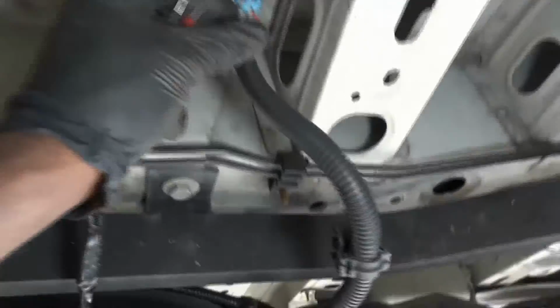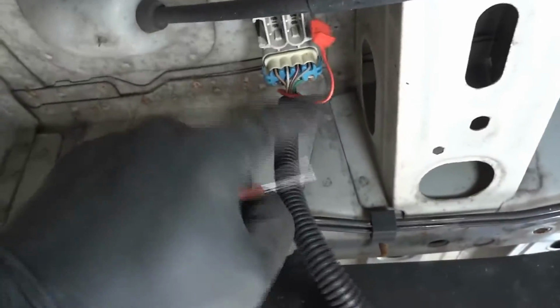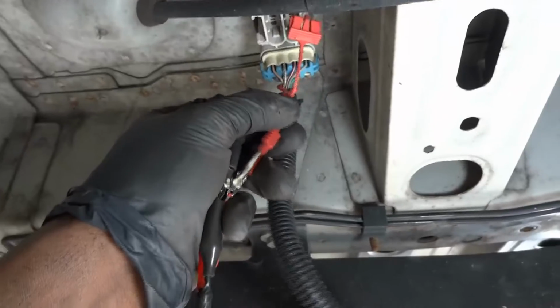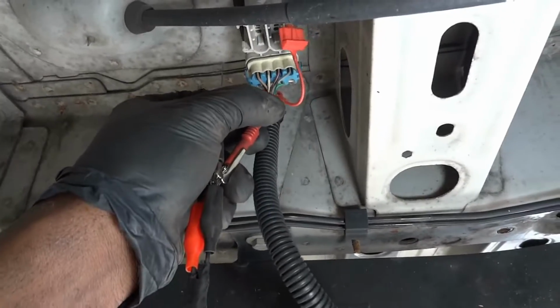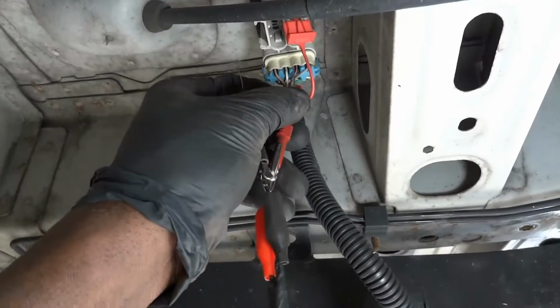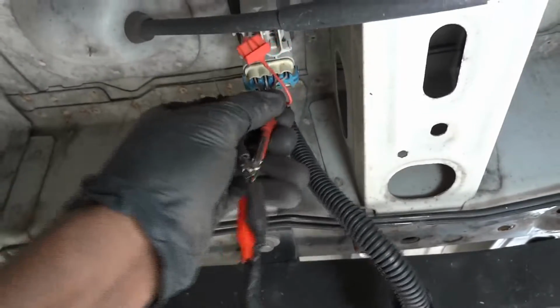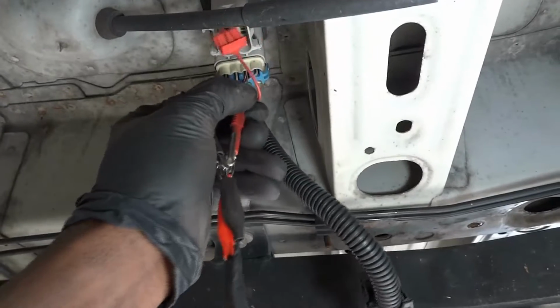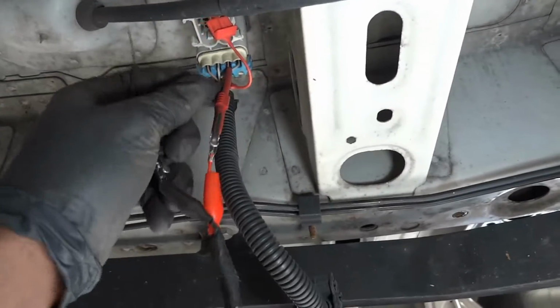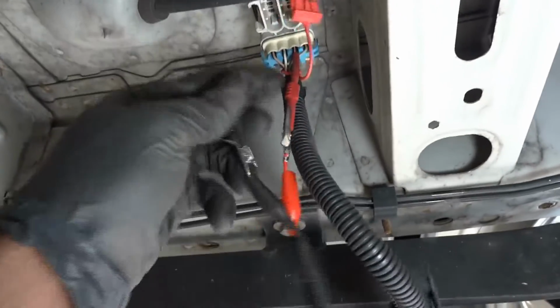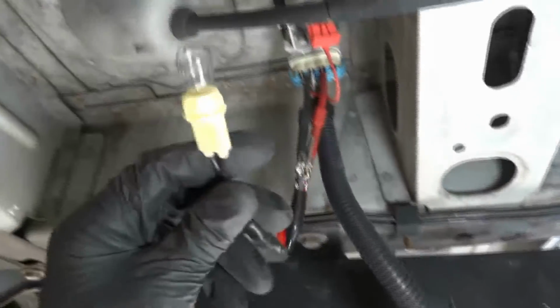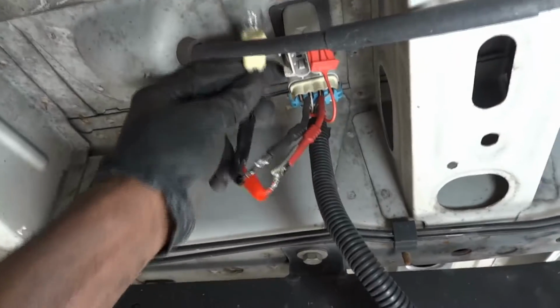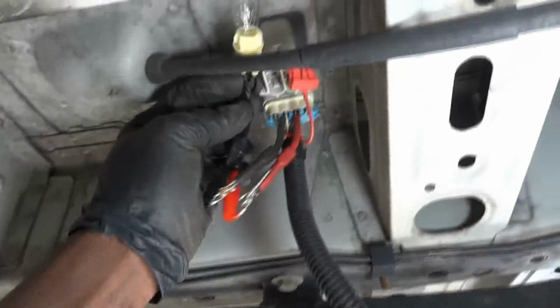Okay, so let's do our test over here once again before we go to the wiring at the solenoid. So we know the red wire with a white tracer is our power supply to the solenoid. Okay, and the white wire is the control wire. So I'm back probing these two wires. So my test light is connected in series.